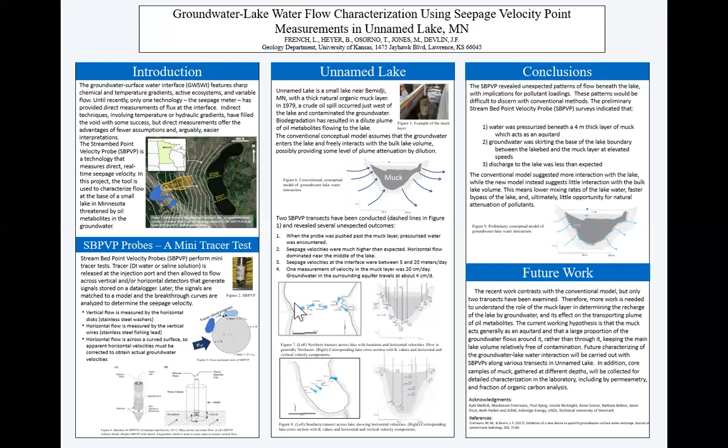In the northern transect, the accelerated velocities along the bottom of the lake were measured in almost every location sampled. Flow was generally to the northeast, consistent with flow directions determined from water level data on the western shore at the end of the lake. In the southern transect, the flow direction appeared to be to the southeast, possibly under the influence of a drainage feature of the lake that permitted water to flow to a more southerly pond.